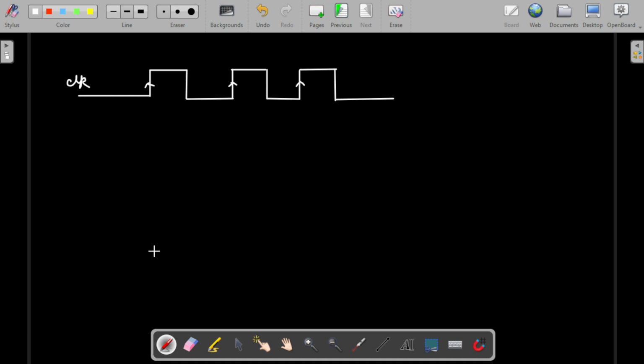Okay, so here we are going to see the frequency division. Whenever the clock is going up, Q is also going up. But the output goes down when the next trigger comes. So this is the time where again it is going down. Whenever there is an upper transition or edge trigger from 0 to 1, only then is the state changing.